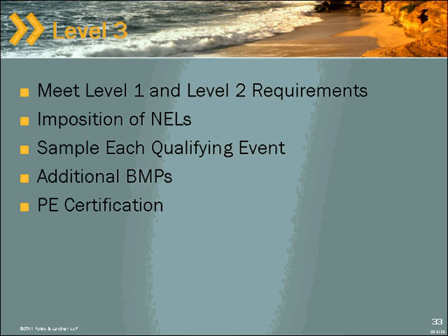for questions, is that these corrective action reports, remember that even without numeric effluent limitation, this permit contains and must contain a prohibition against discharges to waters of the United States that can cause or contribute to the exceedance of a water quality objective. If you have a discharge that exceeds certainly a basin plan standard, probably a Cal Toxics standard, maybe a benchmark standard, that is prima facie evidence that you have a discharge which could cause or contribute to the exceedance of a water quality objective.